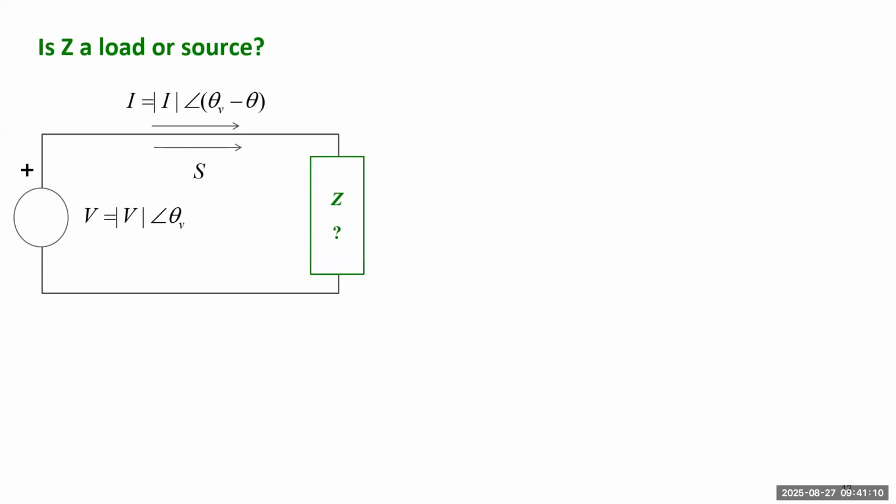So next, let's go back to this simple circuit. Now we have gotten rid of all the sinusoidal waveforms. We just use phasors, complex numbers, to model the circuit. So we have the current phasor, the voltage phasor, and we also have the load impedance. And we define polarity like this. We draw this equipment as a circle. We just assume this is a source, but you can actually define anything to be a source, because in an AC circuit, any branch of the circuit can temporarily consume energy or generate energy. So we don't worry about their actual role.